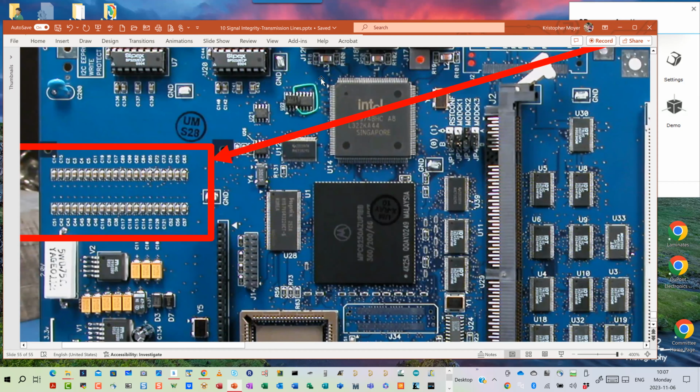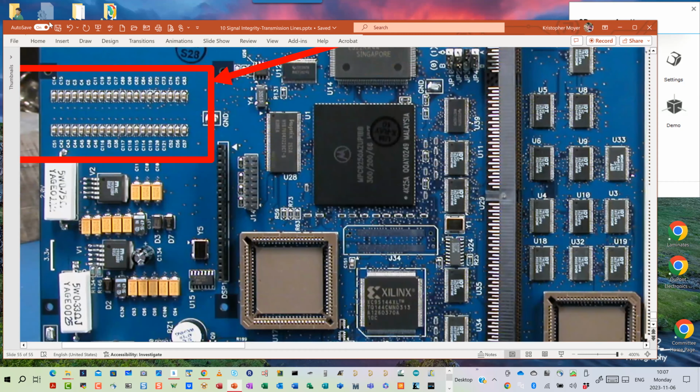Ignore the dead bug green wire solution right here. That was a different design related issue that wasn't on me. But from the board design point of view, this board worked right the first time. Every cap put in a block, end of the board. No problems in my digital section because we properly designed our planar pair capacitances.